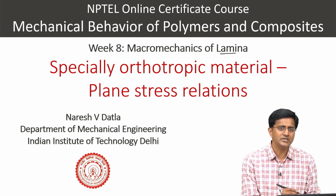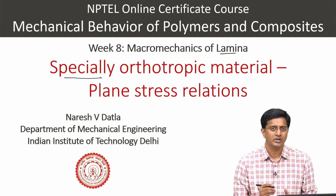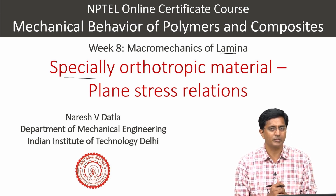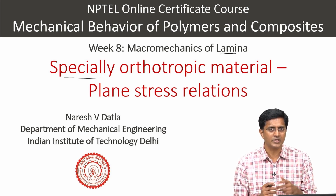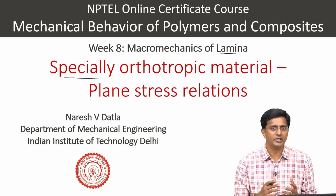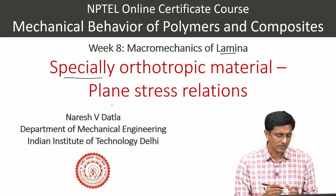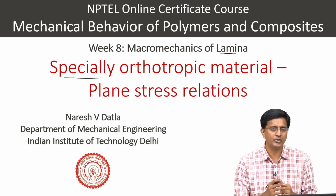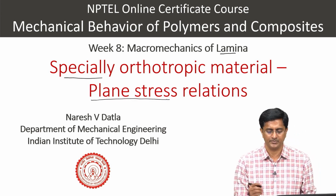In this video specifically we will be focusing on the specially orthotropic material. I hope we remember what specially orthotropic means. It just means that the material has principal coordinates along the axis of the fiber and perpendicular to it. If our choice of coordinate system is aligned with these principal material coordinates, that is when we call it the specially orthotropic material. For this material we will show the stress strain relations, but this time for a 2D state of stress, meaning we will only show it for the plane stress state.